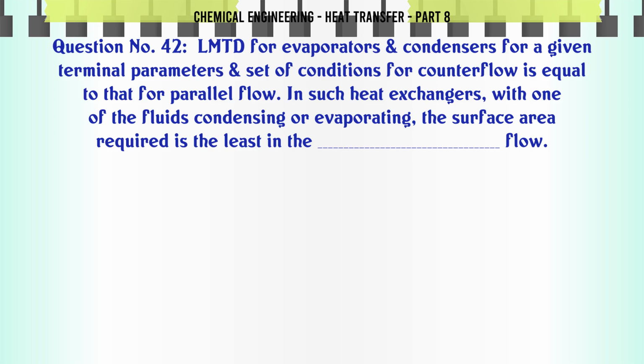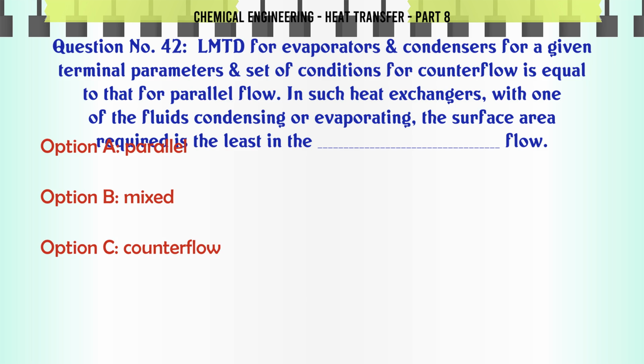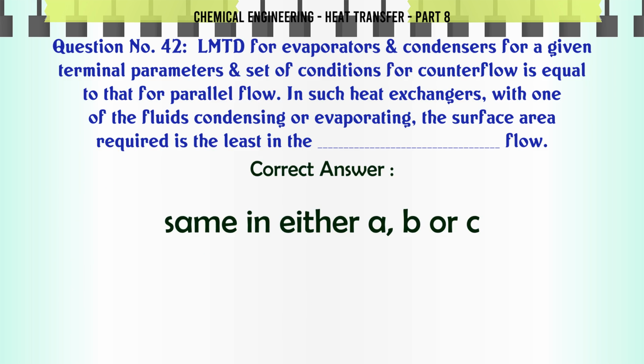LMTD for evaporators and condensers for a given set of terminal conditions for counterflow is equal to that for parallel flow. In such heat exchangers with one of the fluids condensing or evaporating, the surface area required is the least in the flow. A. Parallel, B. Mixed, C. Counterflow, D. Same in either A, B or C. The correct answer is same in either A, B or C.